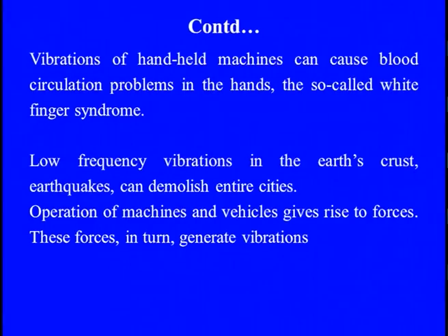So when we are dealing with human vibration, the characterized frequency starts from 0.5 hertz, where the motion sickness is there. From 0.5 hertz we can go up to say 150 hertz or 200 hertz. But when we are talking about machine vibrations, they always start from say 500 hertz, 1 kilohertz or more than a kilohertz only.